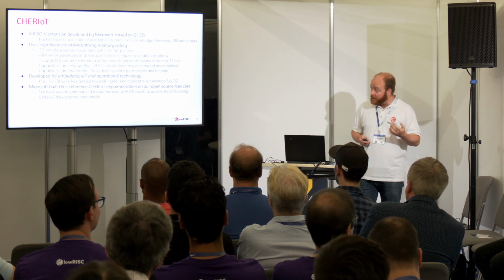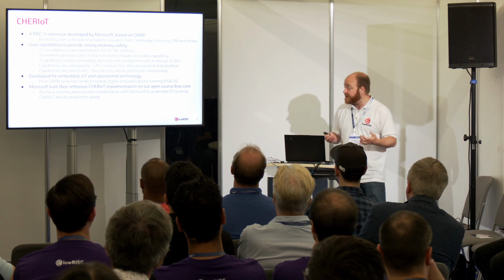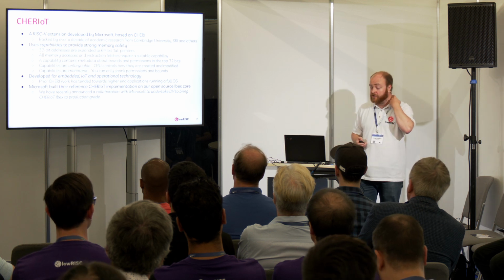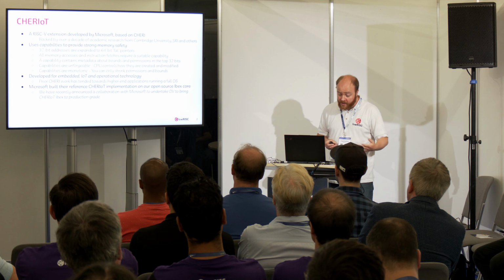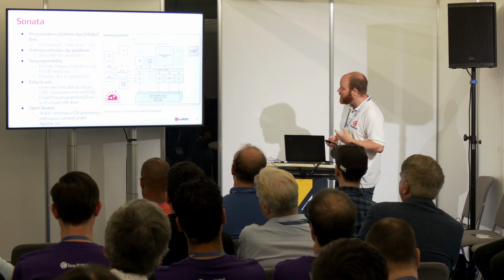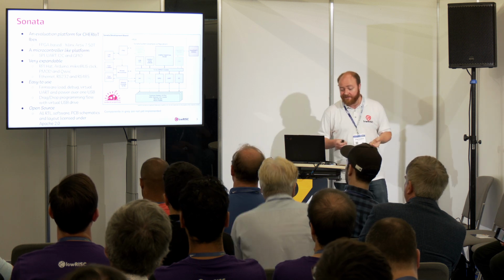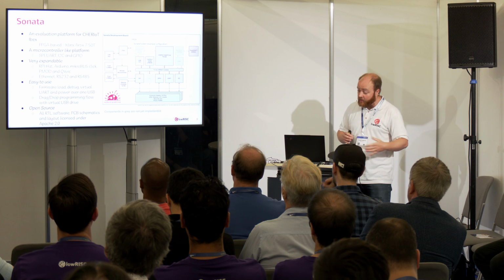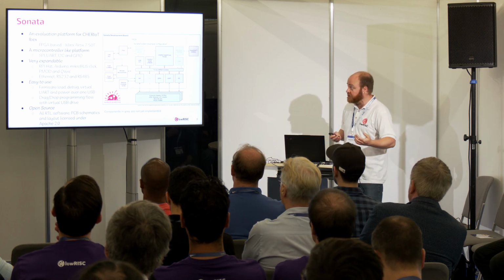Microsoft built their reference CHERIoT implementation on top of our open source IBEX RISC-V core. And we've recently announced a collaboration with Microsoft to undertake DV on this, so we can take the CHERIoT IBEX core to production grade IP. And so the Sonata system is an evaluation platform for CHERIoT IBEX. It's to allow people to use CHERIoT IBEX and try it out in these embedded, IoT, operational technology use cases.